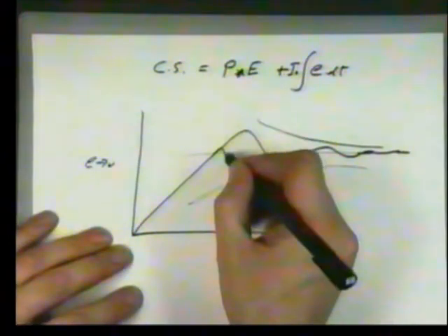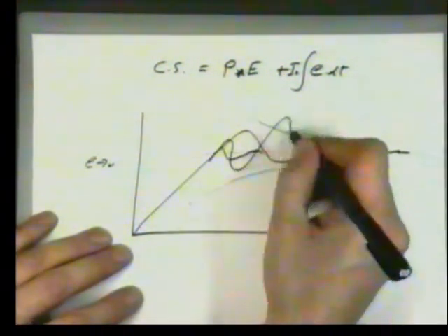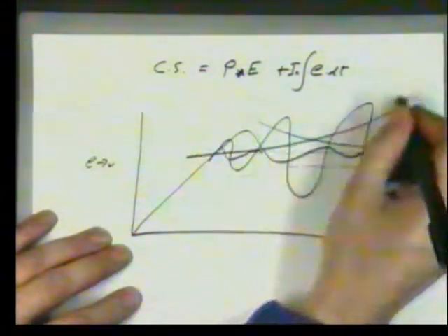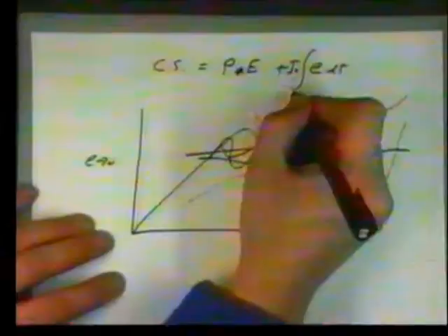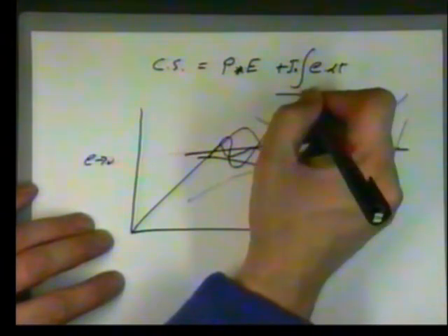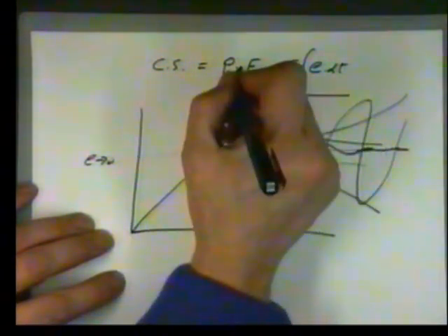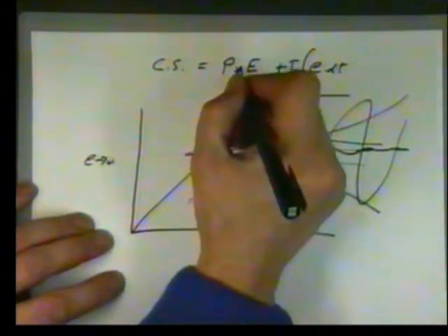But of course it also has dangers, because whenever you introduce a time constant into a system, if you get the timing incorrect, things that oscillate could go out of control. And if you get your sums wrong here, instead of a nice decay, it could instead flip round and you get an exponential increase and your system goes unstable. Why should that be? Well, if you've got an I term that is too large, it can dominate the proportional term and it can drive us unstable.